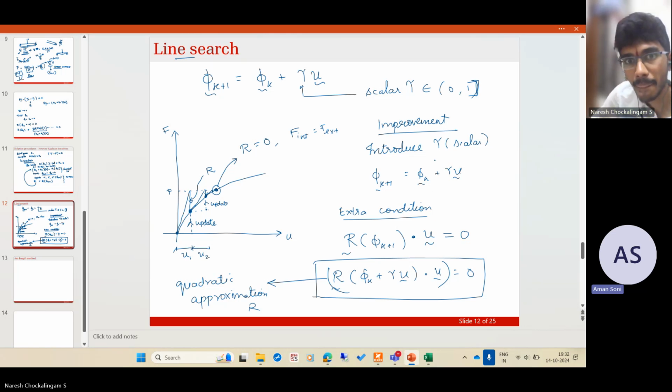So basically, for example, we are getting any FEA problem to do some linearized iterations. For that problem, is it necessary that we have to start with the general, or we can say full Newton-Raphson method, or directly we can jump to this line search method?